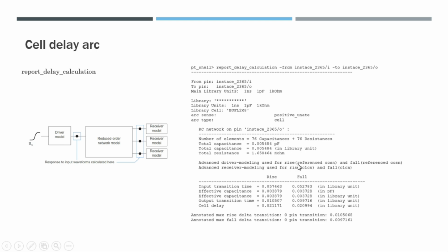So in case it is using NLDM, you should know that the delay we are getting is not so accurate. For PNR level STA, NLDM model is highly used because it will save a lot of runtime and memory. But for sign off, it's a must that we use CCS or CCSN models.